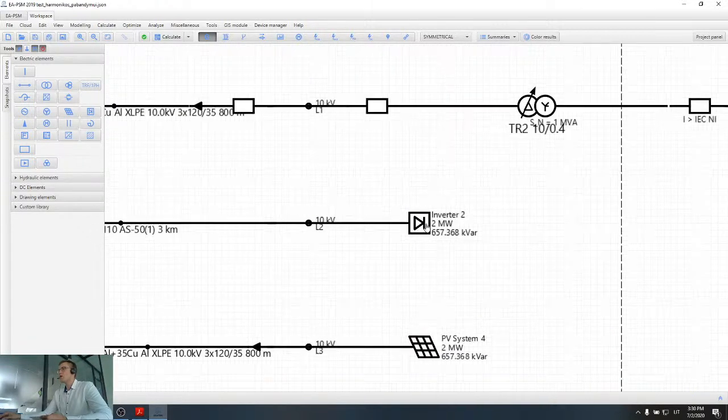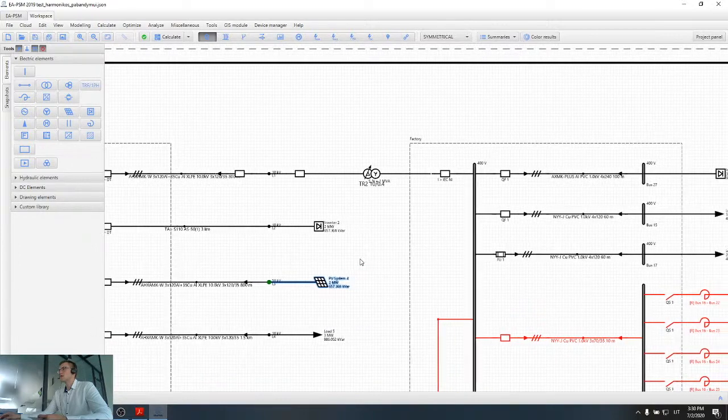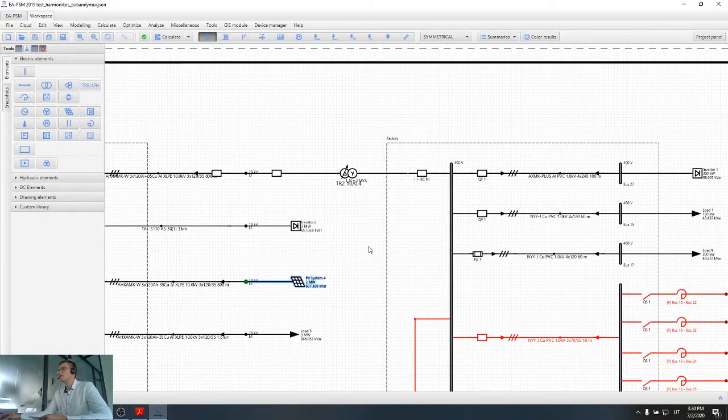Here we have a powerful non-linear load, which could again be some kind of inverter. Inside the software, both of these types of loads, as I have mentioned, are represented as current sources for the harmonics, which creates a higher frequency deviation.